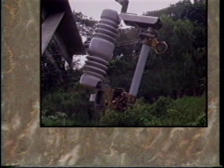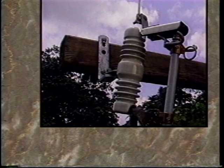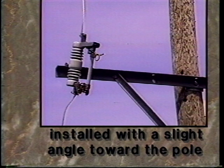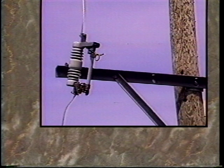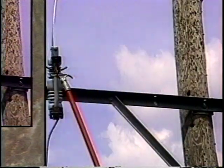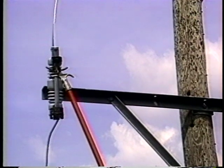A cutout of this type can be mounted on a steel crossarm with a single bolt. It can also be mounted on a wooden crossarm with the metal bracket, which is normally included with the cutout. The cutout should be installed with a slight angle toward the pole. This allows easier operation of the cutout from the pole. An improperly installed cutout will make future operations more difficult.